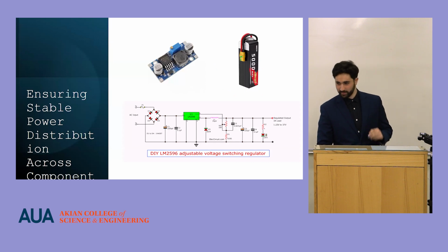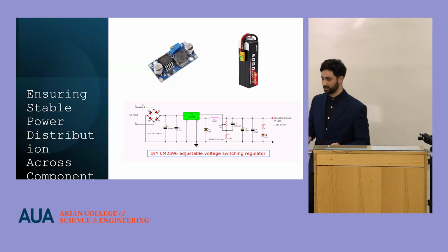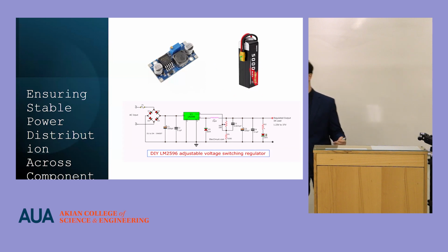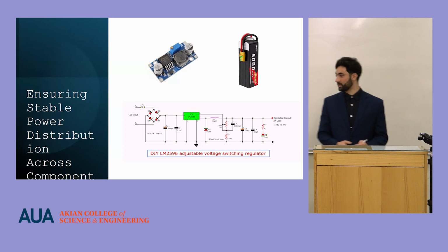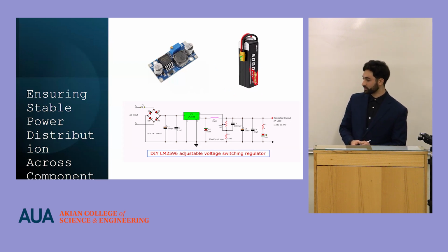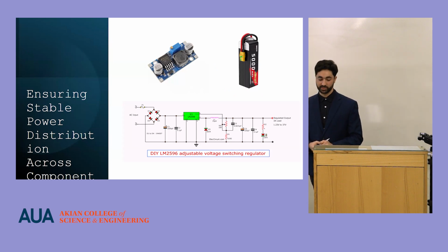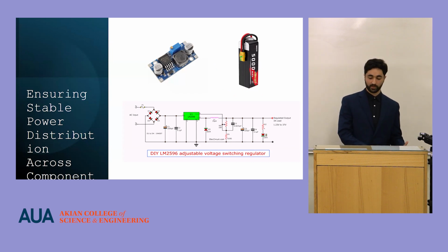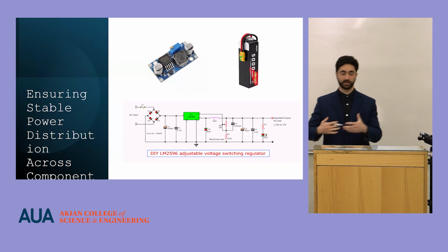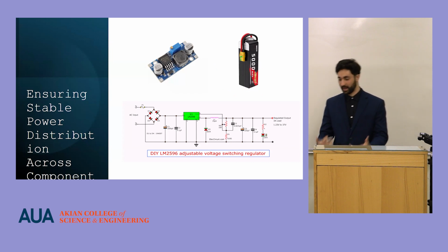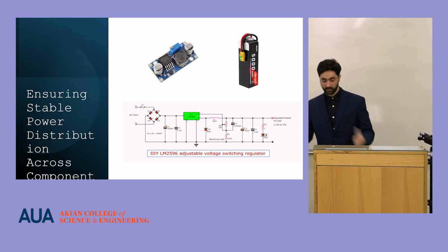And also one more key thing to notice, obviously, as we learned from electricity and magnetism, you should not connect a 22-volt battery directly to a component that only requires 5 volts. So, of course, we used a buck converter, which essentially drops the voltage from 22 to 5 volts. And now all the components have their required healthy amount of voltage, so nothing burns.